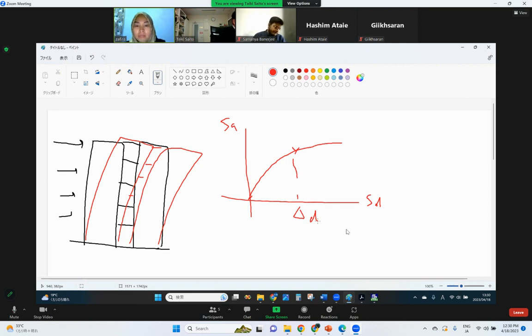In case of hysteresis damper, you check the ductility factor of the wall and the ductility factor of the coupling beam. You remember? Yes, Sensei. And you obtain damping from both ductility factors. But in case of viscous damper, there is no ductility factor of beam.